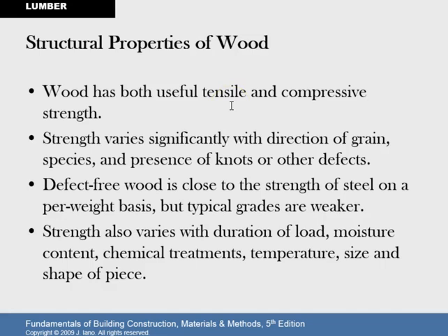And my point, what I was starting with, is that wood and steel both have relatively equal amounts of compression and tension, making them very suitable for beams. A lot of materials are not. Obviously, things like cable and rope have absolutely no compressive strength, and materials like masonry and concrete have very, very little tensile strength. So wood and steel have a nice amount of both, and could therefore be